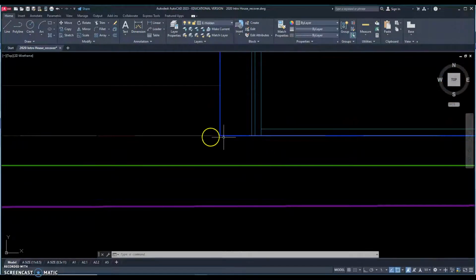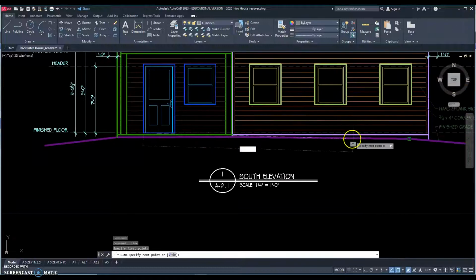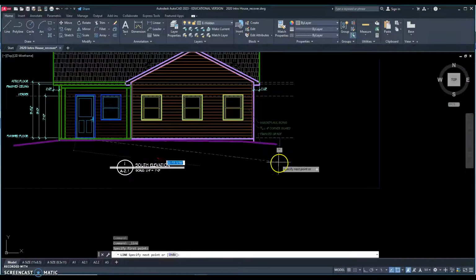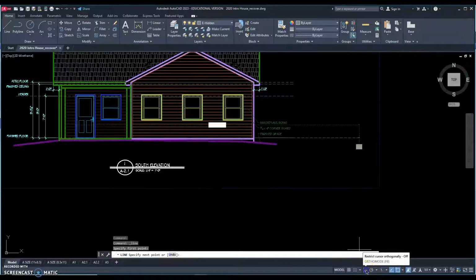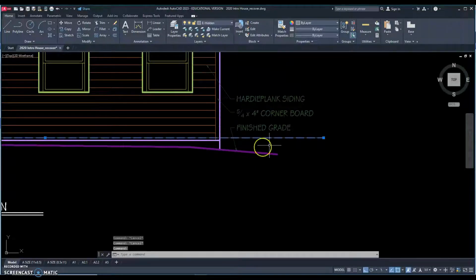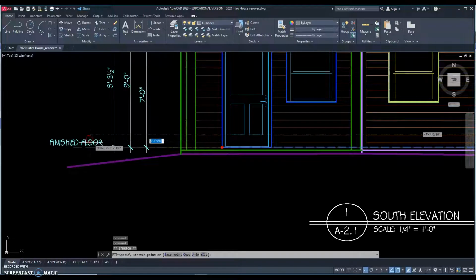So that will be the bottom of the door. Click on the line tool, and we will draw in the hidden line horizontal. Turn on our ortho mode and draw that across the drawing. And then click that same line and place it across.